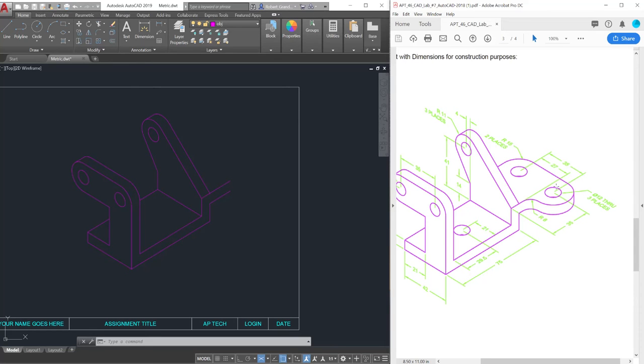So that would be this hole here, and this hole here. So don't forget about this hole. I'm not going to do that for this assignment. You'll be able to figure out how to place that yourself, I'm sure. So what I'm going to do is go ahead and draw this in the wrong location. So I'm doing this without the need of construction lines. So I'm going to select my ellipse command, or this time I'll just type in ellipse. Oops, I got to be in AutoCAD.